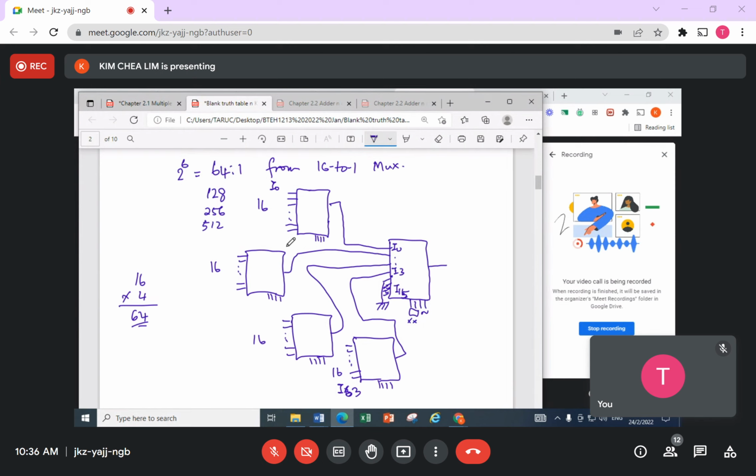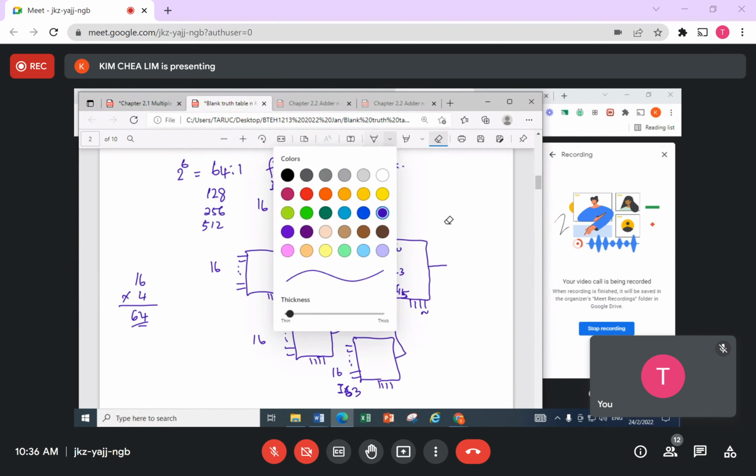So if that is the case here, please, this is not don't care. You must make sure you fix a value to it. All right. So if you're afraid that if you simply put don't care here, it's going to disturb or jumble up your design, what you can do is, whichever ones you are not using, you short them to ground.